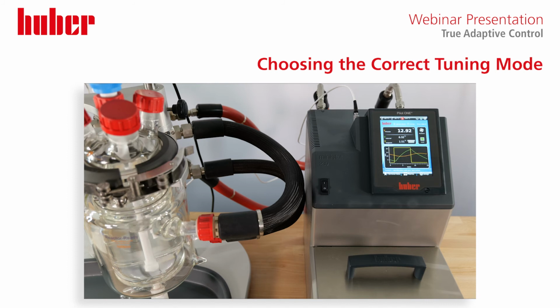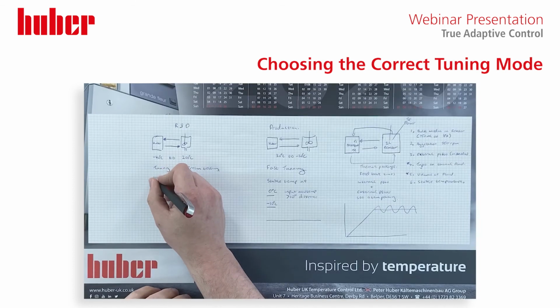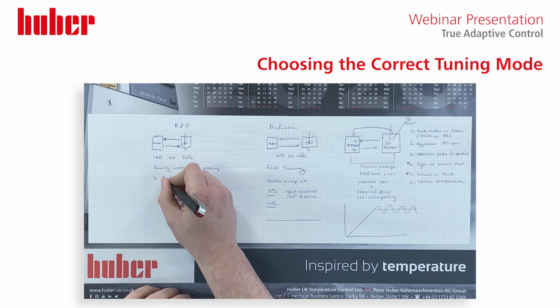And what you'll see is you start with your stable temperature and the machine will then scope out between your minimum and maximum set points, which you've done in the top left hand corner of your Pilot ONE. So we've got a slightly different setup here. So 1, we need our bulk media again.